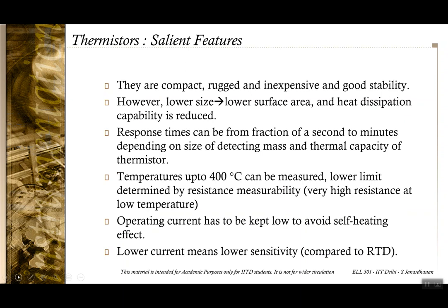Now going further to the salient features of thermistors, because of their semiconductor nature, they can be made compact, rugged, inexpensive and have good stability. However, because of the same smaller size, they have a lower surface area, which means that the heat dissipation capability is also reduced, and the chance of self-heating is increased. However, the same small size also helps in the response time being very small. So you can have thermistors heating up and giving the correct indication in a fraction of a second to a few minutes even. That depends upon the particular mass and the thermal capacity of the